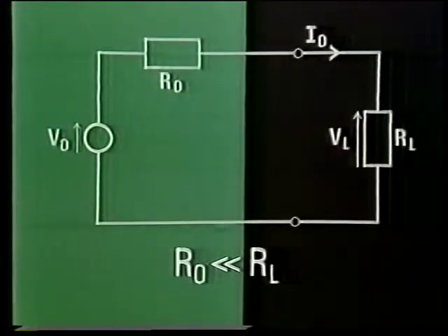But the amplifier we used in the circuit was a 741, which has an open loop output resistance of about 75 ohms. So feedback has led to a considerable reduction in the output resistance. And it is this relatively small resistance which leads us to think of the circuit as a voltage amplifier, because provided the load resistance is 47 ohms or more, the voltage gain of the amplifier does not depend on the resistance of the load. Now, what about the current gain of this amplifier?